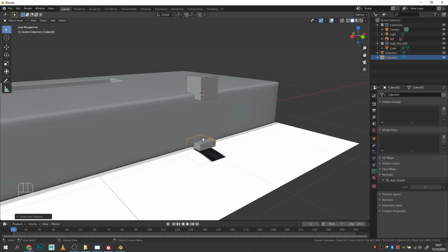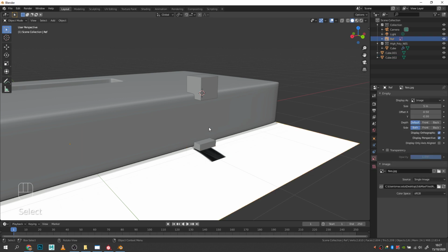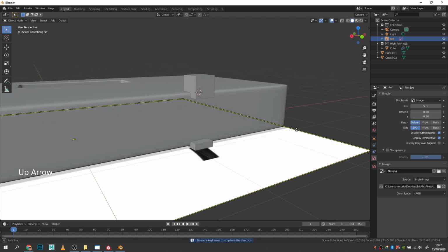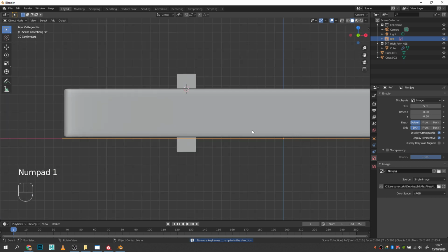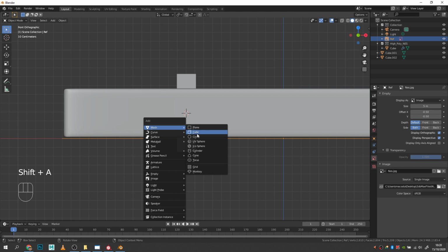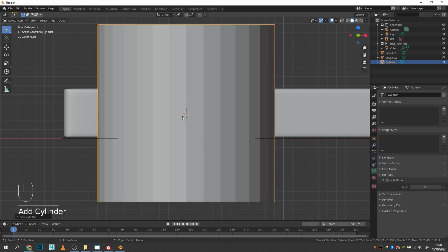Okay, the piece in the middle kind of funnels in, so it's not a perfect, cylindrical hole, it funnels in, so we need to make that. So I'm going to come to a side view, pressing 1 on the numpad. I'm going to Shift and right-click to move our origin point somewhere in the middle here, and then use Shift A, mesh, cylinder. We want that cylinder to rotate towards us, so we rotate it on the X-axis.